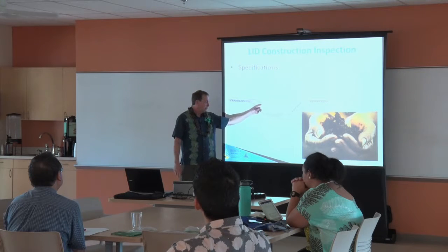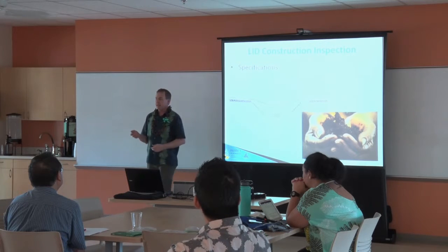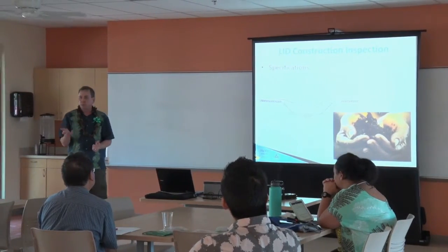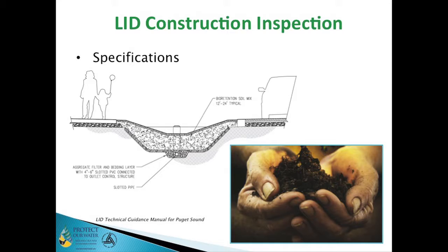We get into this bioretention soil. A lot of jurisdictions have standard specs for it, but it's going to tend to be a lot of sand, a lot of compost, a lot of organic matter. The real simple test I can give you for it is if you can take the soil, get it a little bit damp and make a ball and it holds together in a ball, it's not what we're looking for. And you see the picture there of some of the type of soil we're talking about.